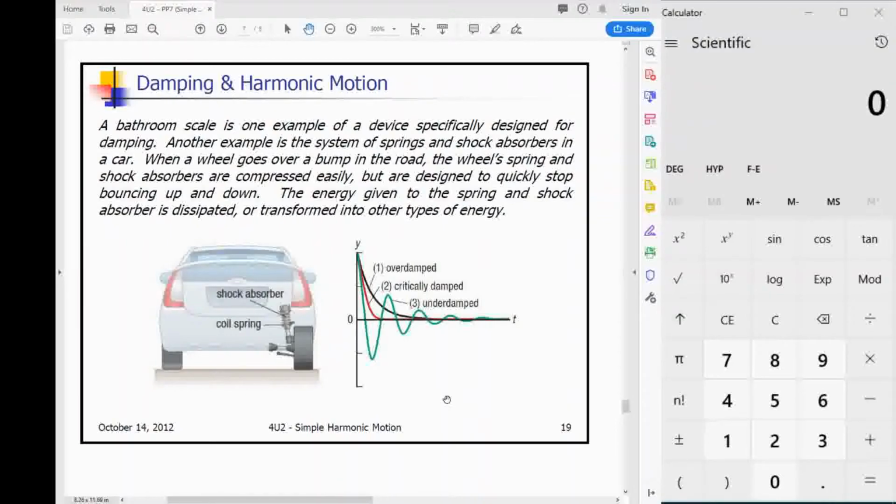The electronics themselves will sometimes even represent something like a 3.2 volts as a 1 volt, or a 6.8 volts as a 1 volt, or as a 1 output. So in terms of the output voltage needing to be a 5, it doesn't have to be exactly a 5, but if it's close to 5, then that's good enough.